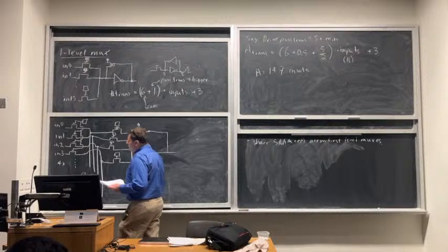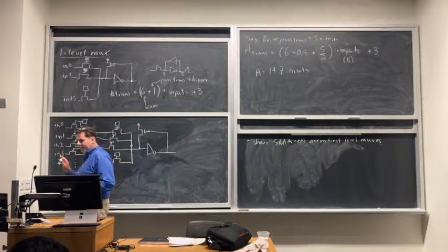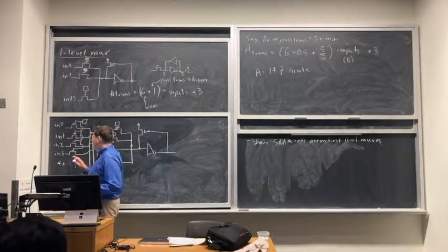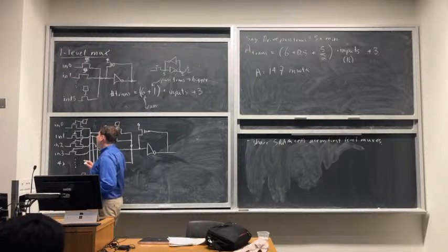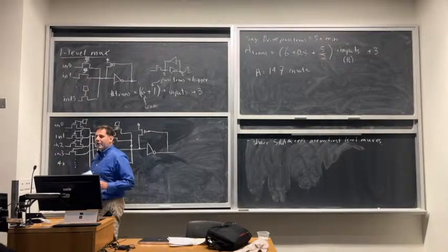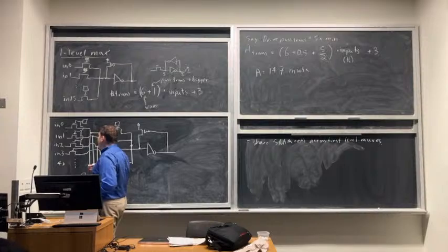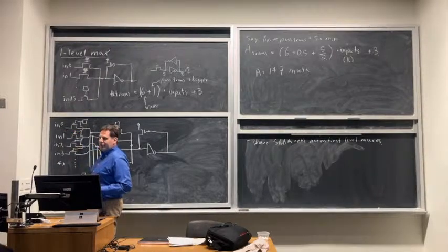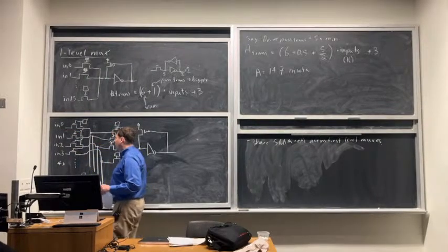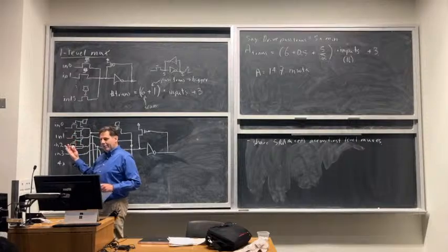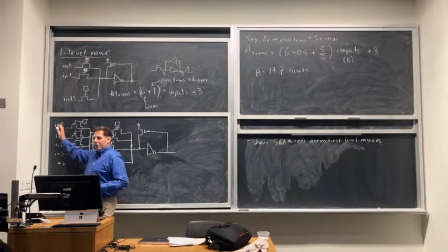This doesn't put any additional restrictions on the CAD tool. So inside the router, the router that's inside Quartus, Quartus has a router that eventually wires together your design. It's not actually told how these muxes are built, okay? It's essentially represented as a graph. So all these routing wires would be nodes.